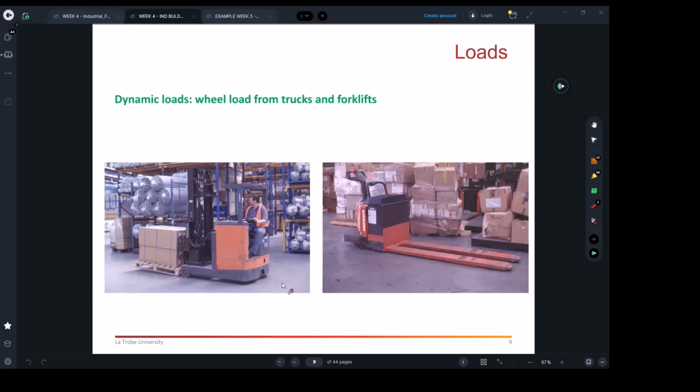It's kind of rubbish. There's a lot of areas in Melbourne where it's just a fill area. Fill means it's not a clay, it's not a sand, it's not a natural material. It's just a fill where things have been thrown, like if they want to create a trend, especially in the Docklands area, or I think Port Melbourne as well. There is a lot of fill where they threw soil material there, and they kept doing this ages ago.